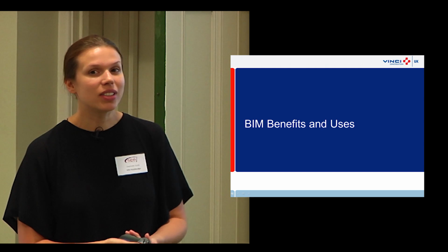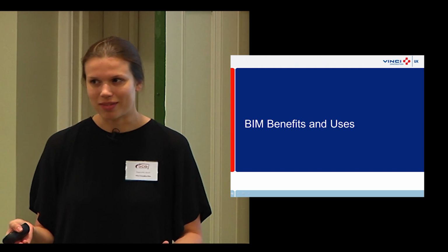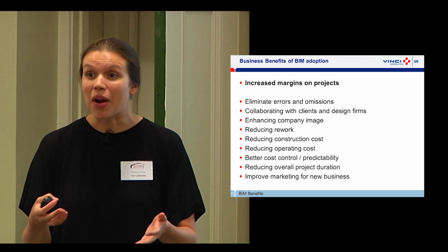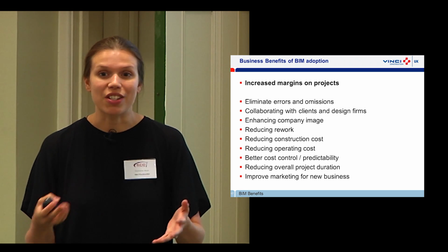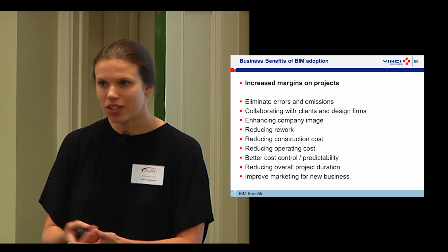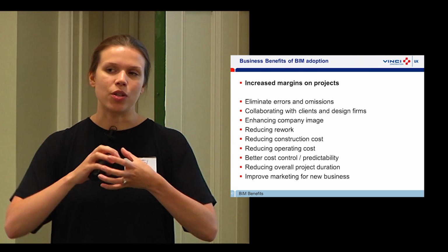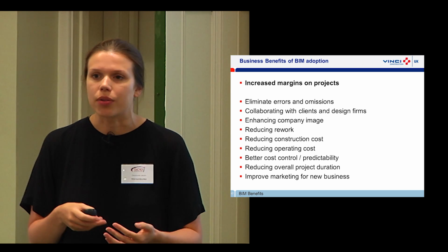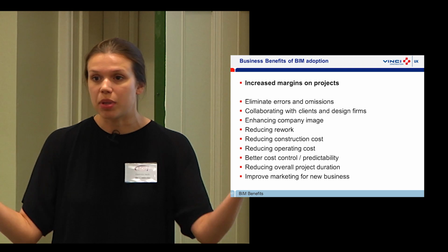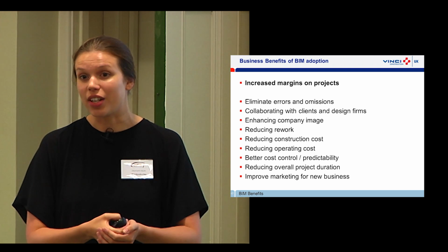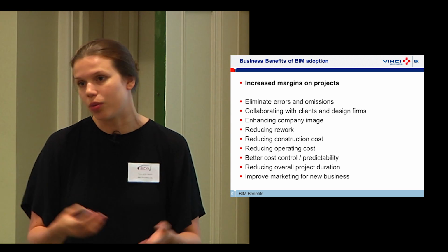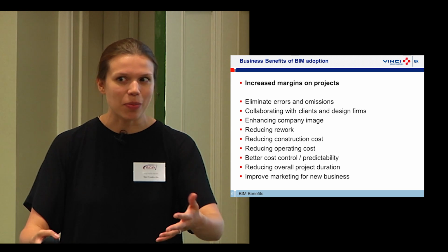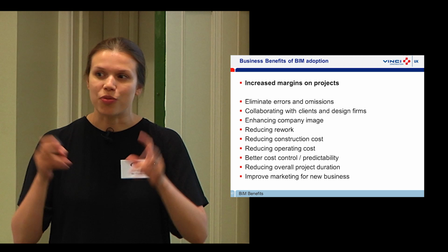Benefits and uses. BIM is not going to save all your problems on a construction project, but it will help with issues, primarily rework or clashes on site. If you carry out clash detection, where you pull 3D models together and check spatially whether they coordinate, and there are any physical clashes, say a piece of ductwork going through a beam, the software will tell you. You're able to create a report and send it out to the design team or fabricators, so you reduce errors by going to site already knowing those problems and resolving them. So you should have a clash-free design.